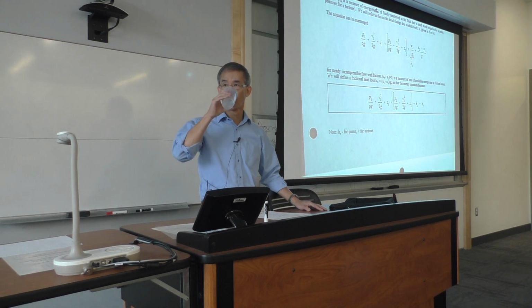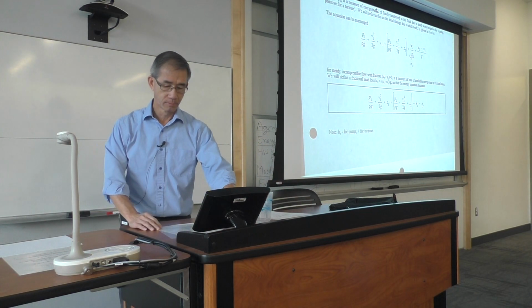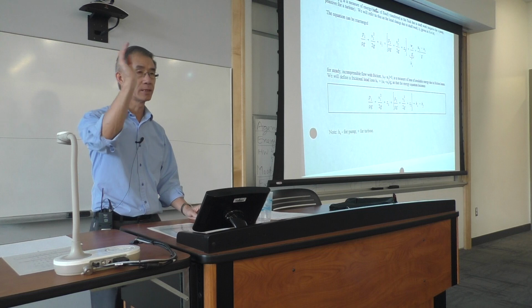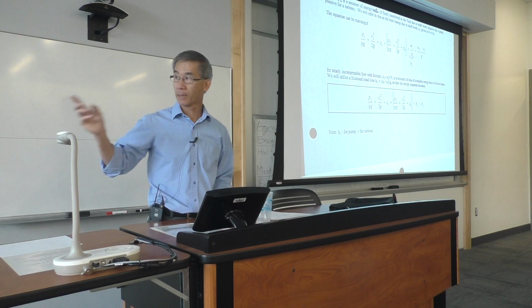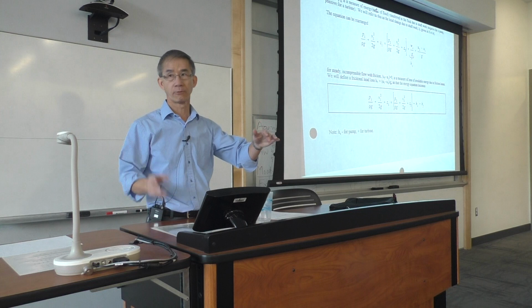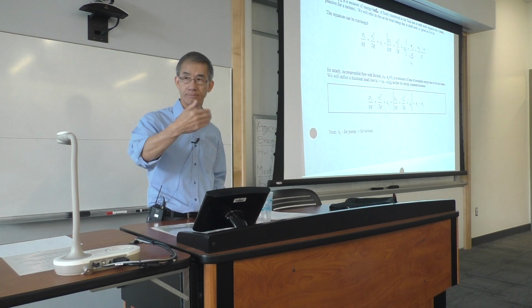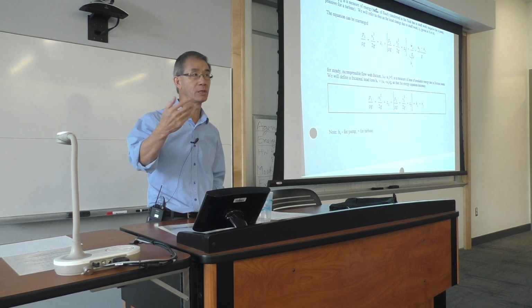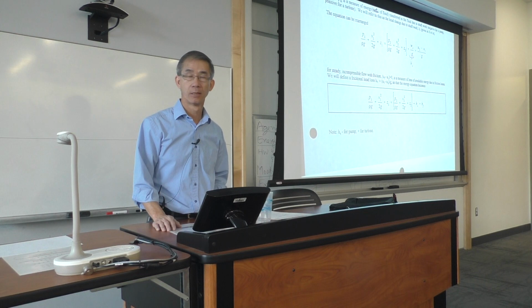Yes? So if you say, for example, that a pump has 100 feet of head, what does that mean physically? If I sell you a pump and say this pump is capable of putting in 100 feet of head, that means when you hook it up to a power supply, and let's say you draw 100 kilowatts, and you have water going in and water going out, the water coming out from the pump has added energy to the degree of 100 feet per weight of the water. So it directly relates to how much work or power can be transferred to the fluid.